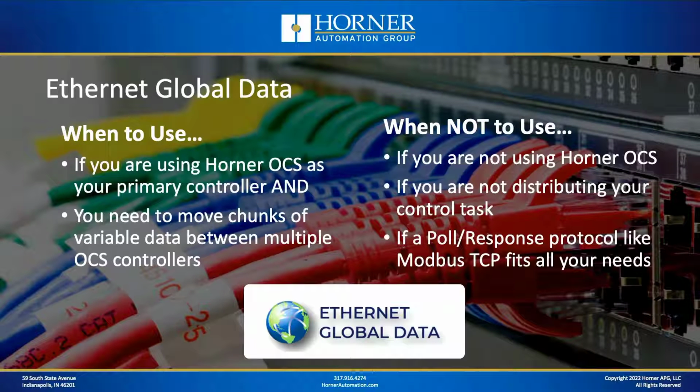Finally, let's talk about Ethernet Global Data. When should I use Ethernet Global Data? So really, if you're a Horner user, then Ethernet Global Data could have some real advantages to you. If Horner is your primary controller and you need to move chunks of variable data between controllers because you've got multiple controllers in the same system, Ethernet Global Data is almost always the best choice. You can get 10, 20 millisecond type response time and be moving literally dozens and dozens of variables and still keep that really good response time. That's definitely a case to use Ethernet Global Data.